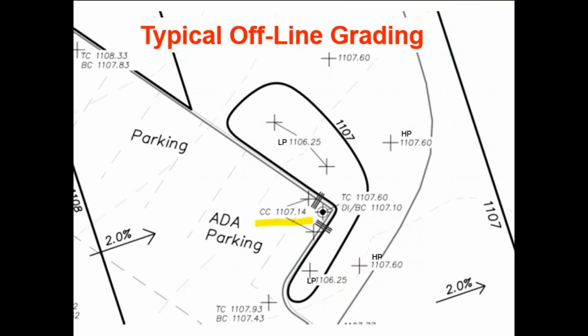We have the curb cuts, we have the low points in the parking lot, we have the high points that show where the berm is, we have the two contours, which you'll always have to have two contours here. We have then the water backing up and into an existing drain inlet. There is no raised drop inlet in this example.